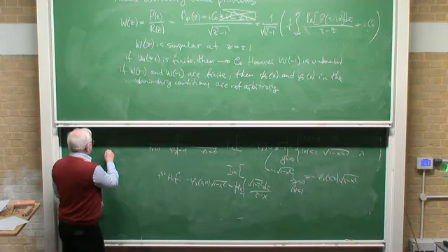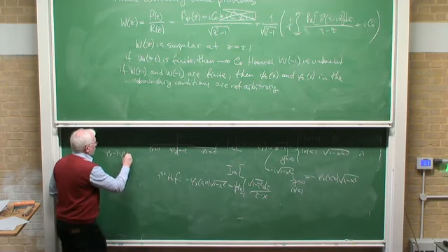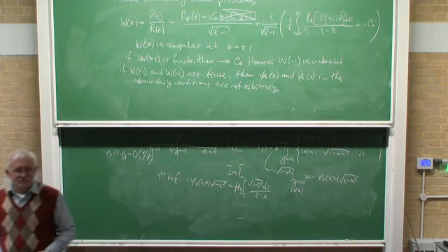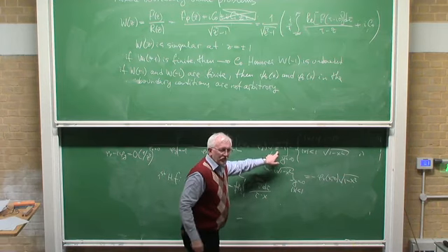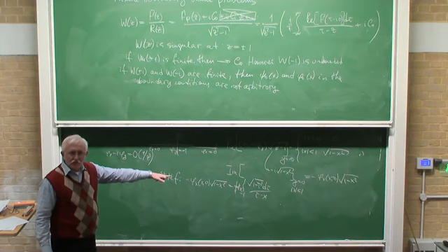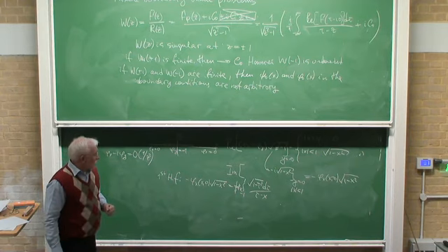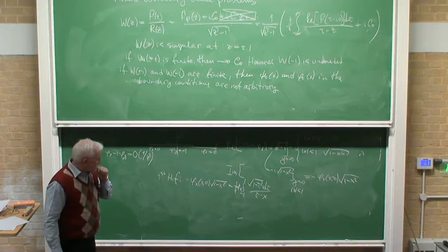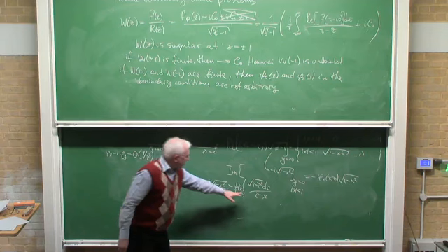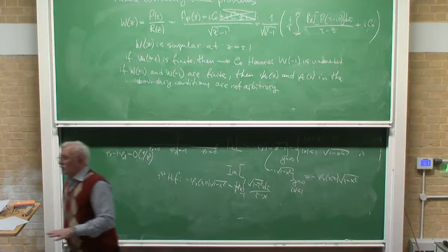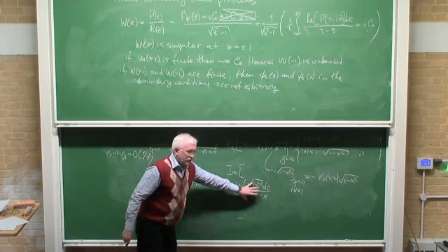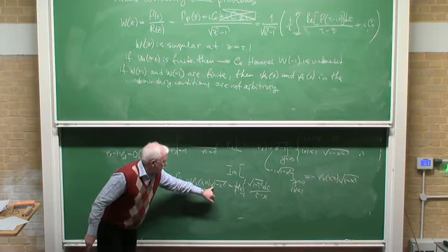In this problem, phi x minus i phi y at infinity behaves as z squared. And once we multiply by the square root, the product behaves as 1 over z. So that is the complete solution. There is no arbitrary additional constant. However, that integral has finite, non-zero values at both x equal to plus and minus 1. And then, to find phi x, we should divide by the square root.